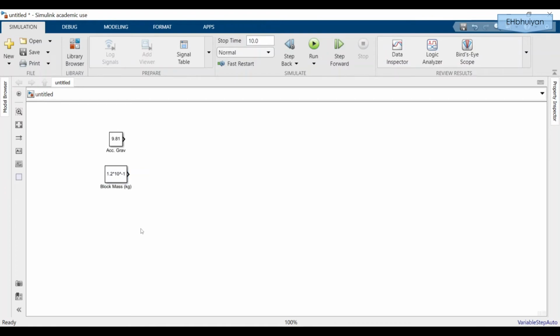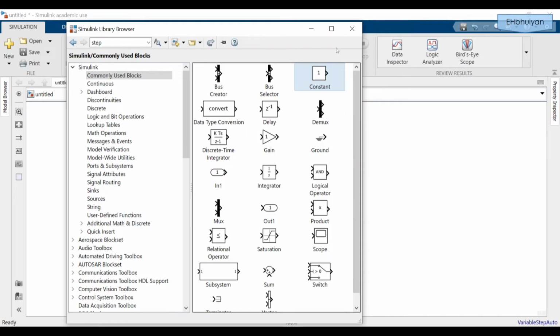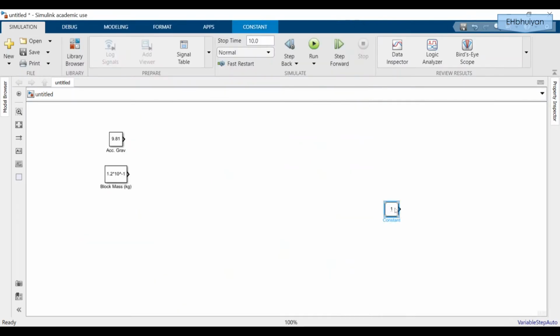What else is constant? Well, the final spring length is constant, as well as the initial spring length. We can do this one of two ways. We could just give the subtracted or the stretched value as one input, or we can have Simulink do it for us. And I'm just going to do it that way. This time I'm just going to go to library browser and insert blocks, just to show that there's a different way to do it than copy pasting.